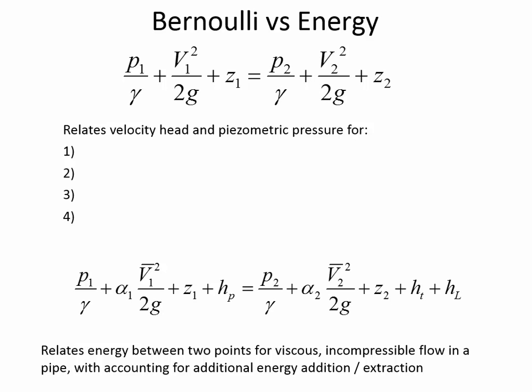If we've got some delta H like this, pressure usually we express in terms of pascals or newtons per square meter, but we can also express pressure in terms of just how many meters of water is there above that location. And so in the same way that we sometimes express pressure as a height, we can express energy as a height.